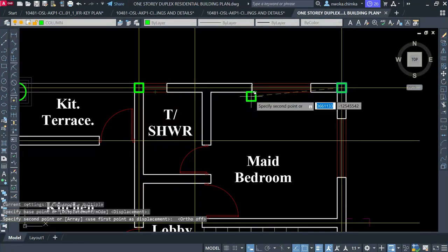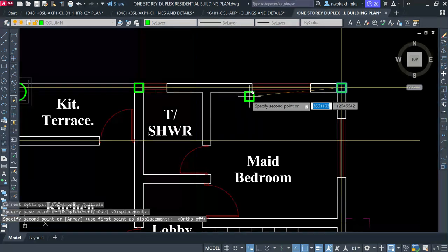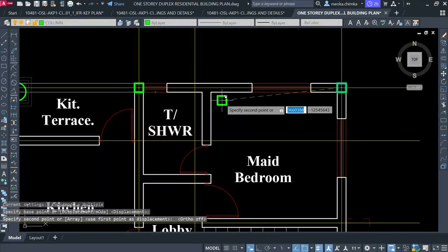If you have a 7 meter or 8.5 meter beam, you can't use a beam depth of 450, which is the lowest depth of beam to use for a floor beam. So for someone beginning design, to not have these kinds of failures in your design, always keep your column distance below 6 meters.